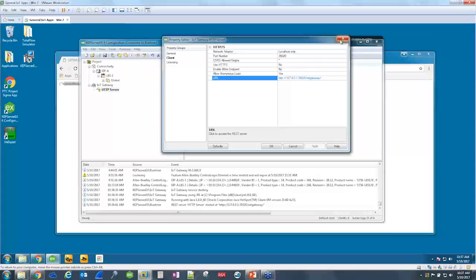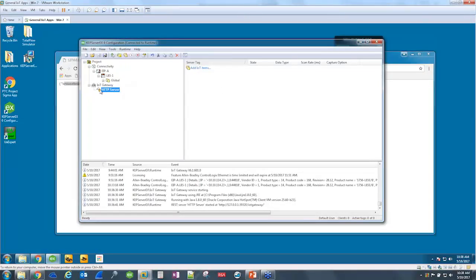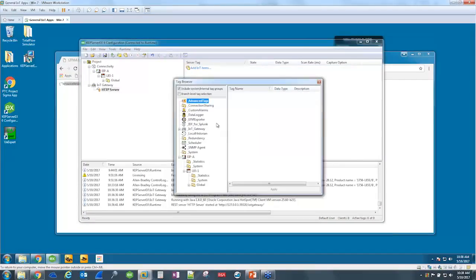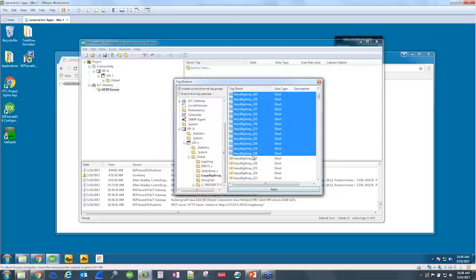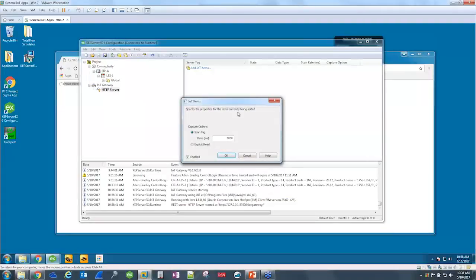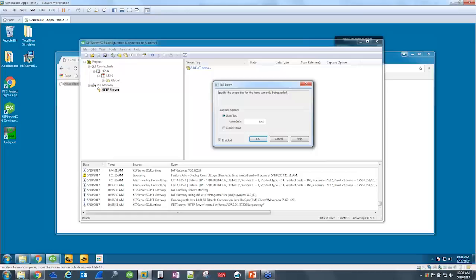One is a simple sampling, and then clients are reading from cache. So that's fast access, non-critical, you don't need to know specifically at that moment in time what the value is in the controller. Oftentimes though, especially for manufacturing execution, it's important for the MES to understand, at the moment that the MES asks for it, what value is present in the connected device. And so when we do something like that, we offer the explicit readability per tag or per data point. When a read comes into that particular object, that'll actually activate the driver to go read from the device, versus just setting up the driver to scan at an interval and then all clients are just reading from the web server's cache.